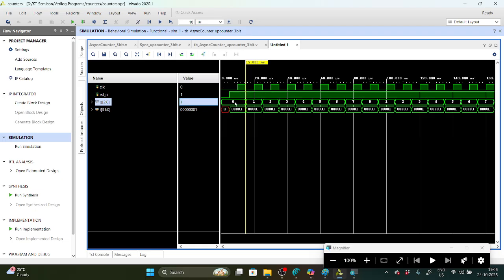So that means reset mode to functional mode is synchronous with the clock, that I told you, no? So reset removal is synchronous, but reset applied is asynchronous. Asynchronous, irrespective of clock and inputs, immediately it will reset the circuit. Here I didn't do it in the test bench, you can analyze that. During the negative edge of clock, the counter is incrementing.